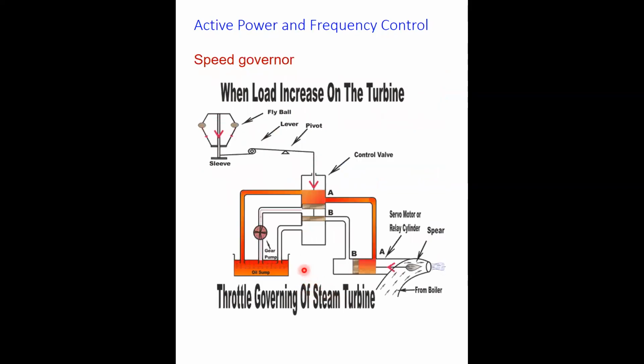So that's just to show how the governor works, basically. This is the case of a hydromechanical type of governor. So there is a fall here, and as a result, you find that the piston is pushed down. This piston is pushed down, and then you have the pump of oil through this piston on this side of the valve.